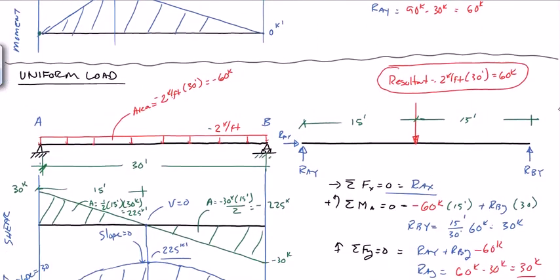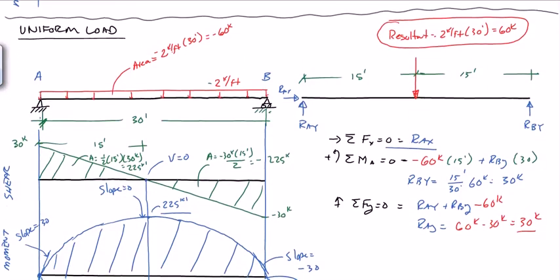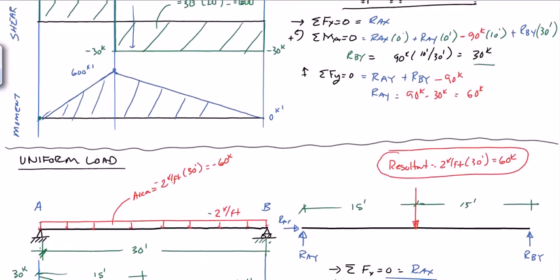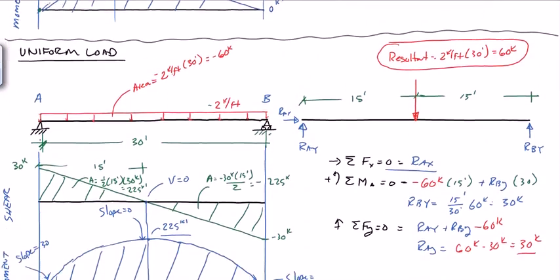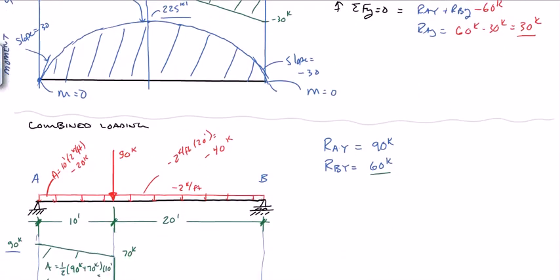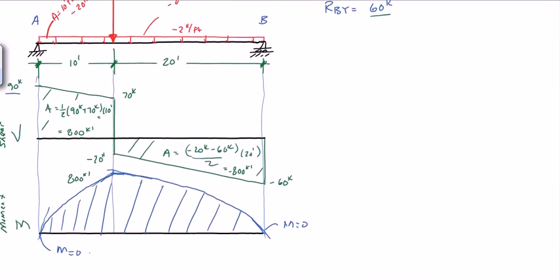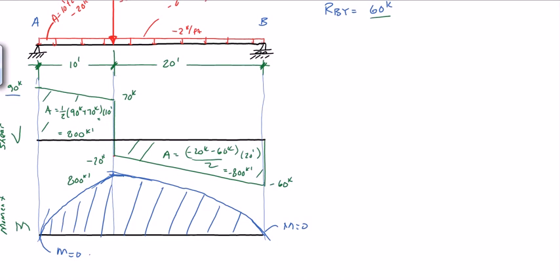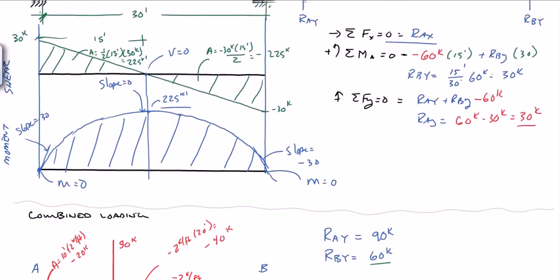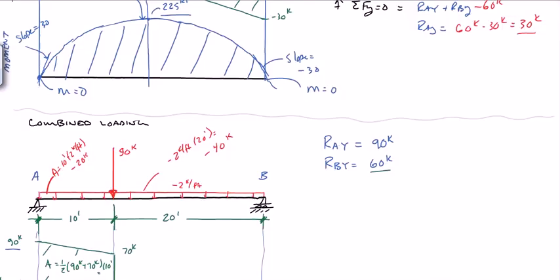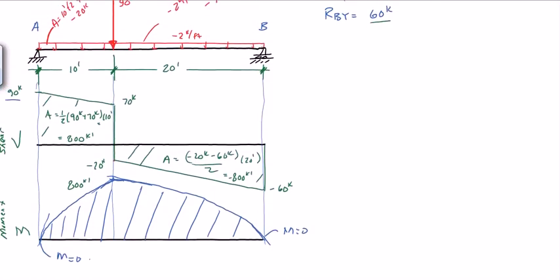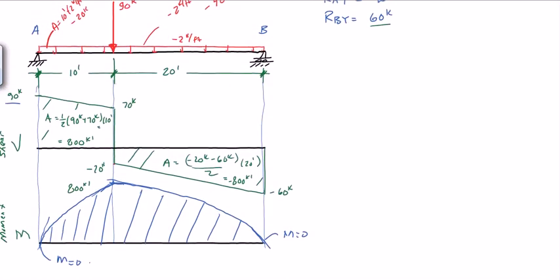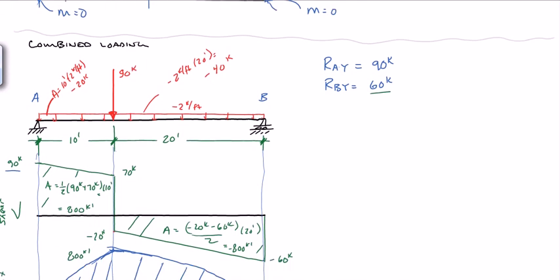It's 600 on one of them and 225 on the other one, and they happen at 10 feet and 15 feet, but the maximum moment combined happens at 10 feet over. So you can't just add the two together. We can't just take the 225 and add it to the 600. We actually have to do it mathematically. So I'm going to complete this one here, and then I'm going to do another one after this where I can show what happens if we try to do the shear and moment diagram of this using the resultants.